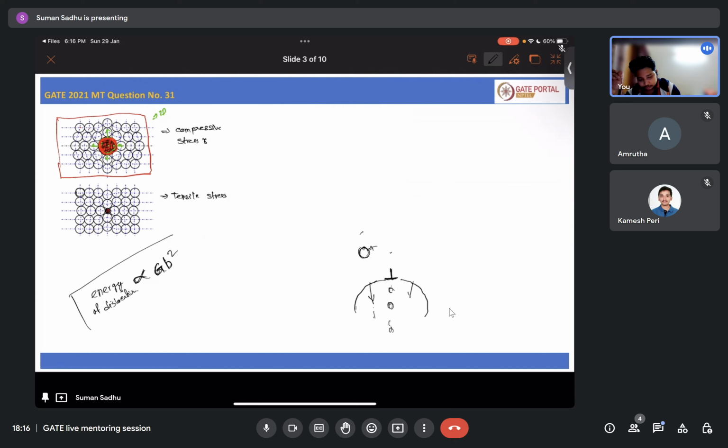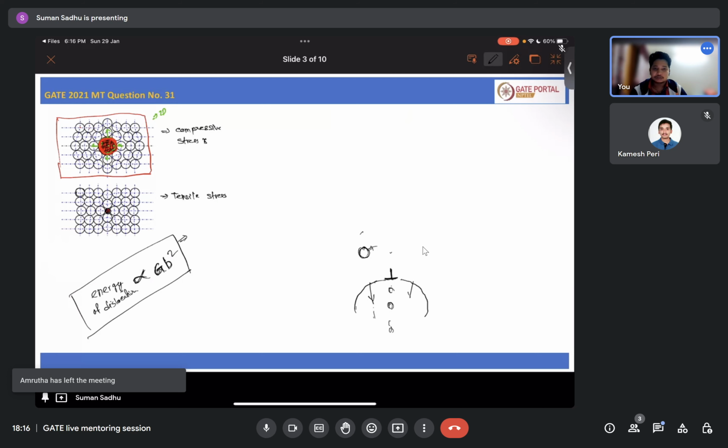So in case of screw and edge dislocation, some other terms will be there, like nu and all these things. But that is not the concern in our case now. In our case, it is mentioned that as this solute atom is locally modifying your modulus, basically it is locally modifying your G. In this case it is not an effect of size, it is an effect of the modulus of your atom.